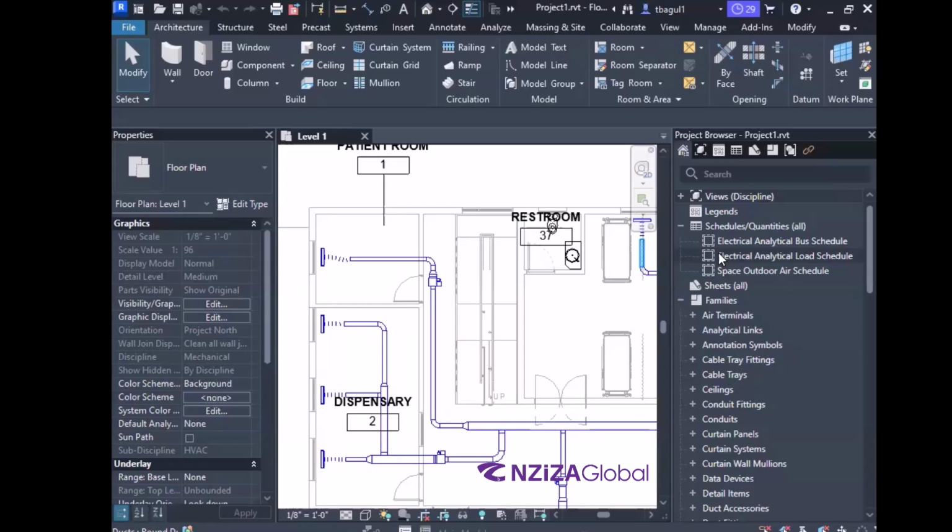Make sense? Now, you introduce an elbow over here. That will increase the pressure drop because air is taking more effort to go through that turn in the duct, right? Instead of going straight. In the VAV box, there is a damper, right? That damper will also add to the pressure drop, right?